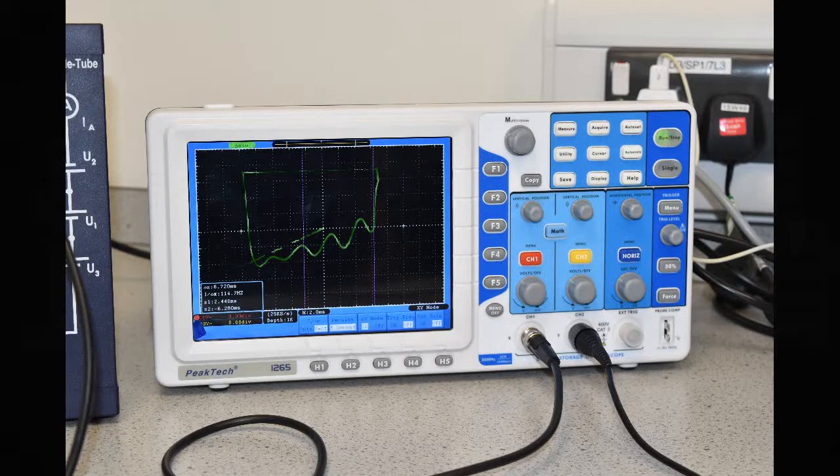This performs a voltage sweep from 0 volts with an error of plus or minus 0.05 to 99.90 with the same error, 0.05 volts. While it's sweeping, the oscilloscope should be paused so the waves can be easily seen, and the time distance can be measured with the cursor for more precision.